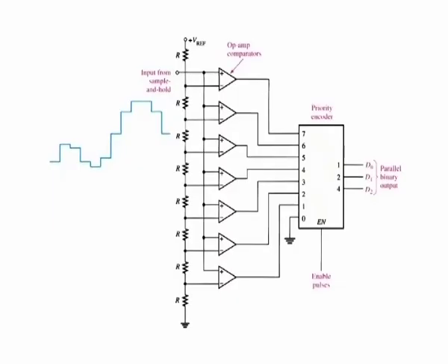Flash analog to digital converter. As shown in this figure, the flash method utilizes comparators that compare reference voltages with the analog input voltage. When the input voltage exceeds the reference voltage for a given comparator, a high is generated. This setup shows a 3-bit converter that uses 7 comparator circuits.